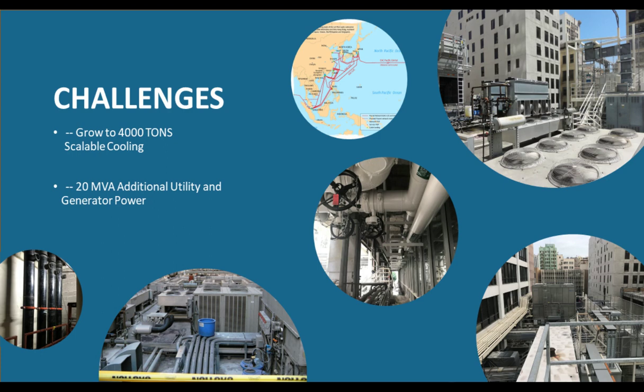So this is really where the story begins today. The cooling towers became a trade-off between size, footprint, and efficiency. The key point that we're going to cover today in detail is the maximizing of the free cooling hours given a 67-degree supply water temperature.